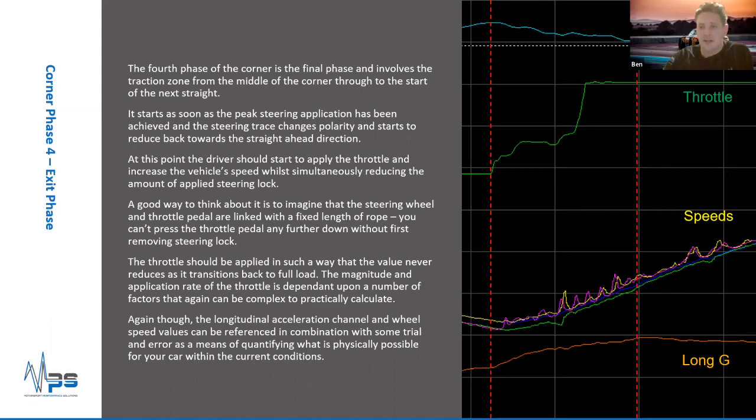So that's very common, and if I could say what would be the most common thing I see, it is this out of sync, out of timing combination between throttle pickup and the peak steering angle. So that's why they're essential parameters for me.